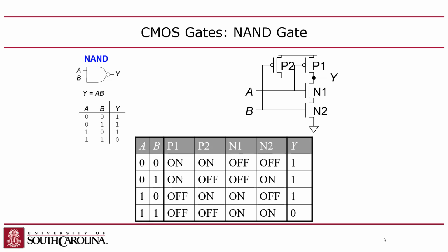Now you might say, why are you mentioning this? Because you can't build an AND gate with this. If you look at an AND gate, the only way you pull up is if you have a 1, 1 as the inputs. But you couldn't possibly build that gate, because if you have a 1, 1 as your input, there's no way to activate any PMOSs, so you can't pull up.